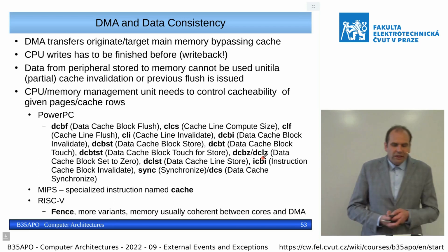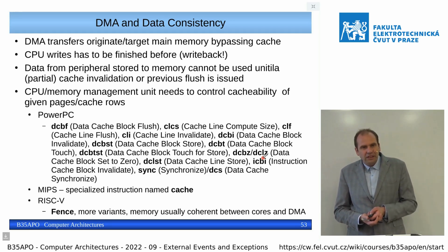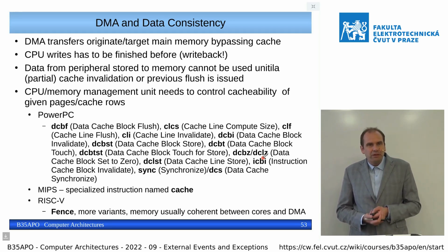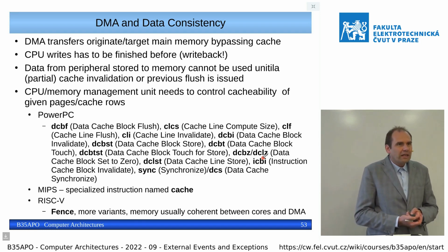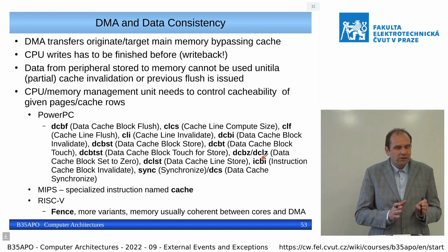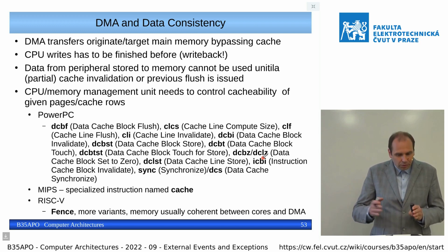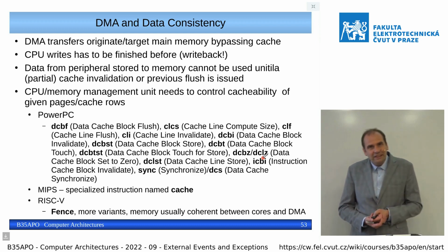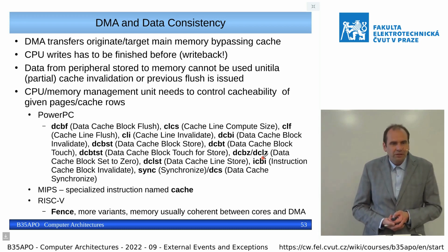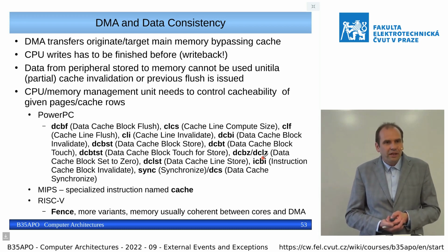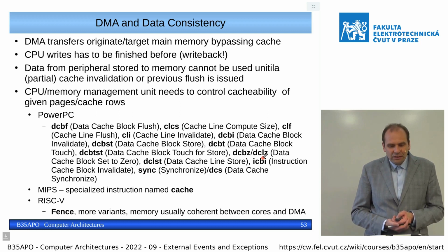For sure, if you have a target where you need to ensure DMA consistency, then the first thing is that you need somehow to ensure that consistency on the level of the processor and write-back queues and so on. On the x86, there was no thought about this when the architecture evolved at the start, because it is an architecture from 1980. So it has no such instructions.